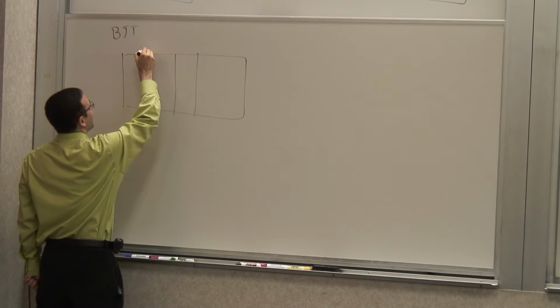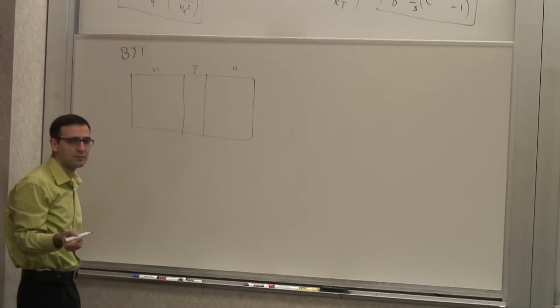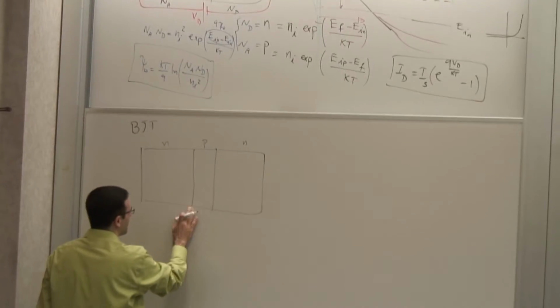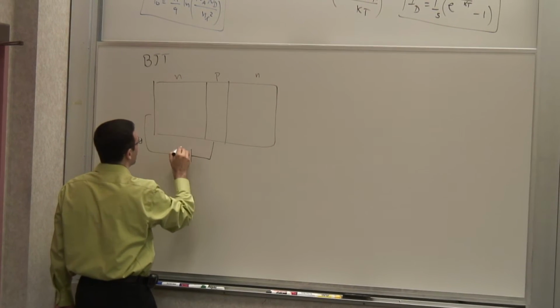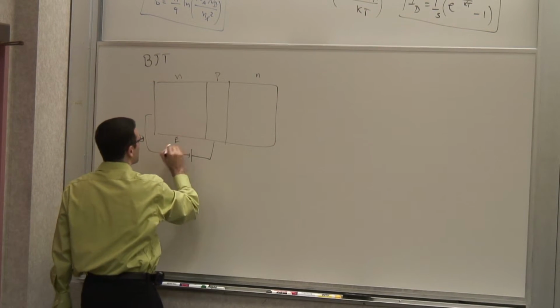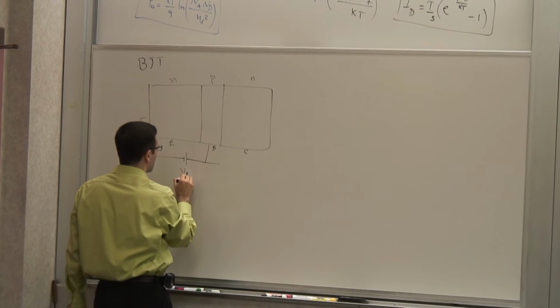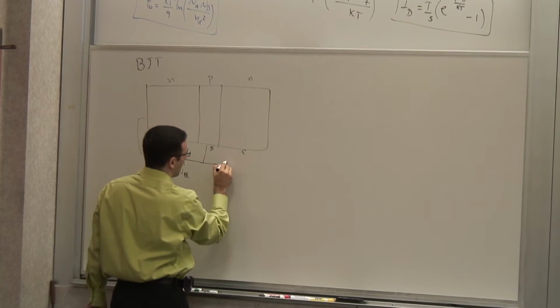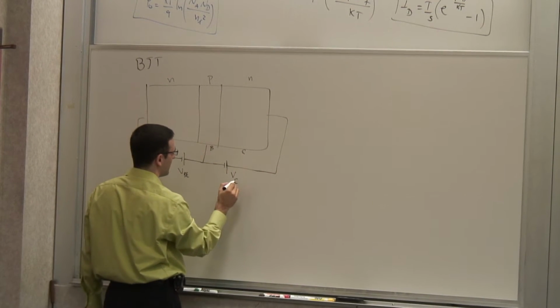So we had a diode, so we had an N. This is an NPN, and you can have a PNP. But let's talk about the NPN for now. And if you forward bias this junction, we call this the emitter because this was where the electrons were emitted, the base, and the collector. So we forward bias this junction, V_BE, and reverse bias this junction. Let's call this V_C.